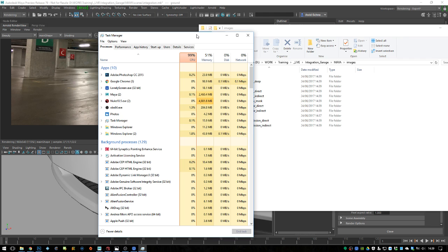Yes, diffuse all at once should be on 1. Diffuse, spec 1, it's all 1, and then mostly it's camera samples. Depends, if you have interior scenes, you obviously need more diffuse bounces. If you have lots of shiny objects close to each other and you need to see all those reflections, you would need to increase your specularity as well.